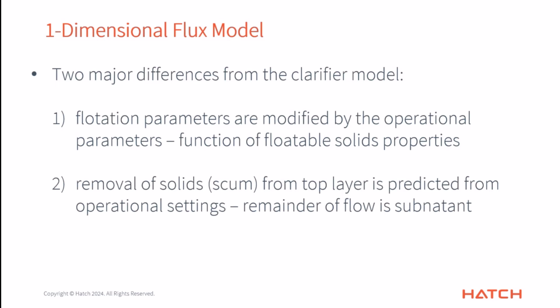And then secondly, this is actually the more important one. The removal of solids from the top layer is predicted from the operational settings. In other words, you don't set the rate at which the solids are being removed; it's predicted from the model. So we have a flow coming in and a flow going out, and the remainder is our effluent, our clean water that comes out as the subnatant. That is very different from the clarifier model, where we set the RAS, the underflow flow rate, and of course the wastage flow rate.